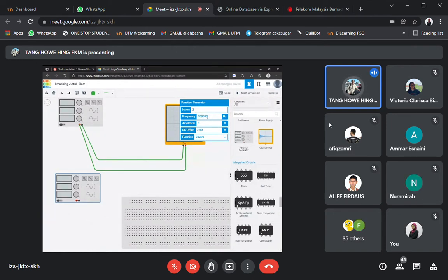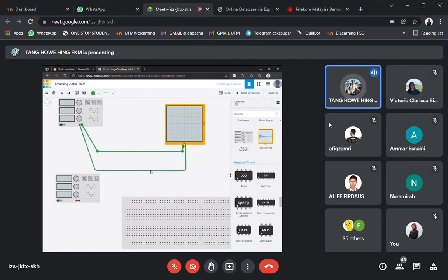So 3 is kilo and then 2. Yeah, so this is 100 kilohertz. And amplitude, the same thing. This round, I think I'll make it somewhere around 0.5 volt. Okay, maybe 1 volt. The DC offset is also at 0. All right, so now I have another sine wave.